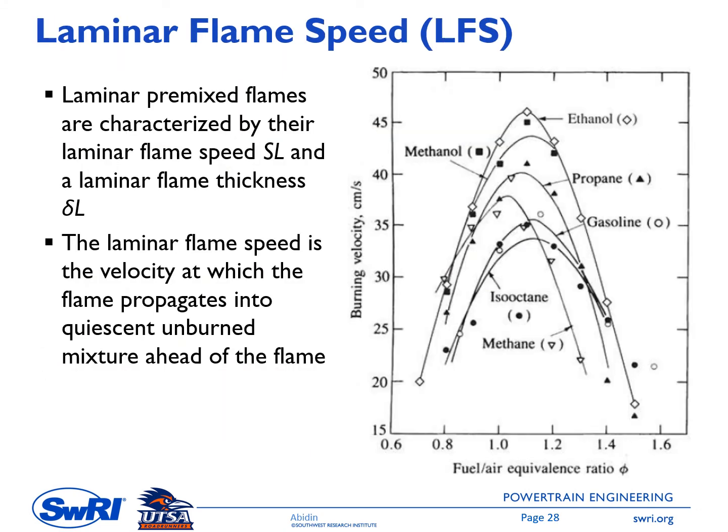Next topic is laminar flame speed, or LFS. So we talked about this LFS several times previously. So let's take a look at this LFS in more detail. In this case we have laminar premixed flames, and the LFS is used to characterize this laminar premixed flame along with the laminar flame thickness, delta L.